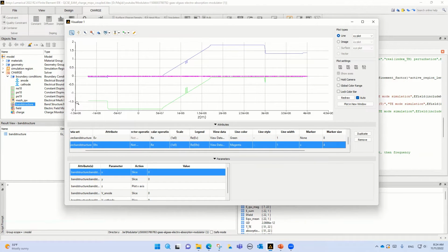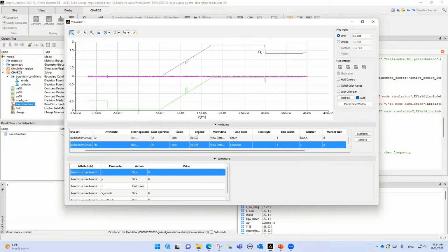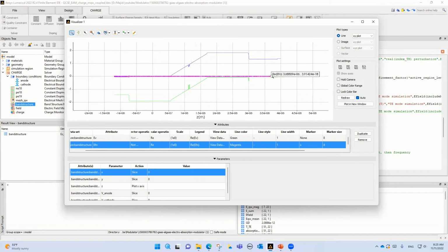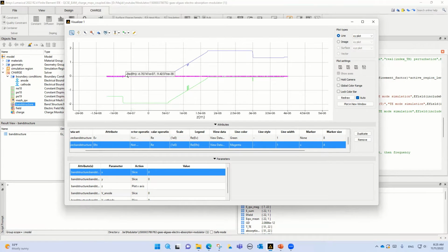Here is gallium arsenide in this region. This is our InGaAs, indium gallium arsenide, superlattice. And also this is InGaAs. This is our quantum well. We have two quantum wells. Our quantum well is GaAs. This is InGaAs, and again this is InGaAs, and this is GaAs, but P-type. You can see here, this is our N. This is our P-type. And here is our N-type. So it's clear.